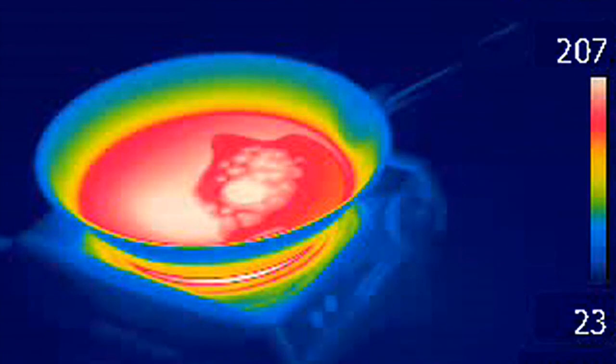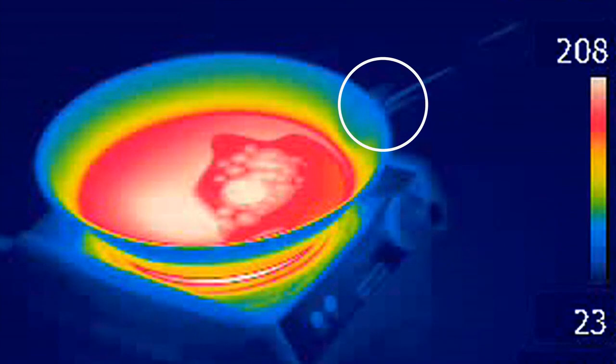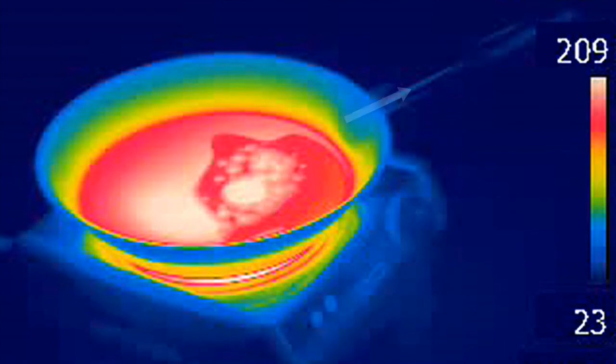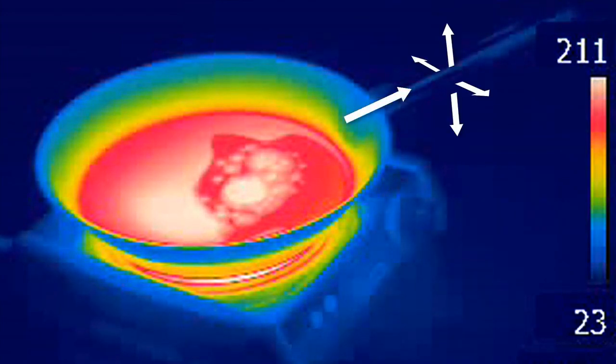Let's look at a thermal image of the pan after it has been left on the stove for 30 minutes. It looks like we predicted in case 4. A very small portion of the handle is warmer than the room, but most of the handle is at room temperature. Remember, this does not mean that the handle is in thermal equilibrium with the room. There is a constant but small rate of heat flow from the pan to the handle, and an equal rate of heat flow from the handle to the room. The handle was designed to reach a steady state temperature that is comfortable to hold without a glove. This is a well-designed pan.